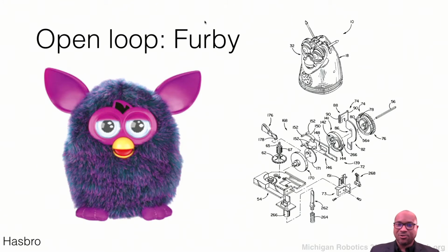You can encode all the behaviors that you just play open loop onto this cylinder, which does very basic playback. And you can do this really cheaply. Whenever you want to call up a particular behavior, you just move the playhead of the tape to a particular location, and then you just play it. This produces interesting behavior that is very compelling. It just goes to show that design sometimes is more important than sophisticated controls or sophisticated mechanisms. And this is pretty engaging because they've sold a lot of these.